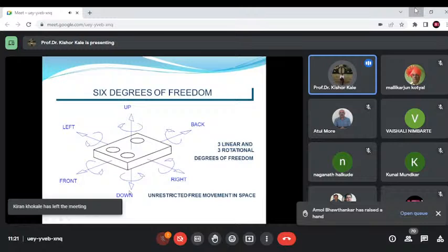So the coordinate measuring machine: you can see over parts with free-form surface are generally inspected by using dedicated fixtures and coordinate measuring machines in an offline mode, not online mode. CMM uses a contact measurement technique which has high accuracy, repeatability, and reliability. Contact measurement techniques are very slow in acquisition of data. This is important. This is their advantage. This is its disadvantage.